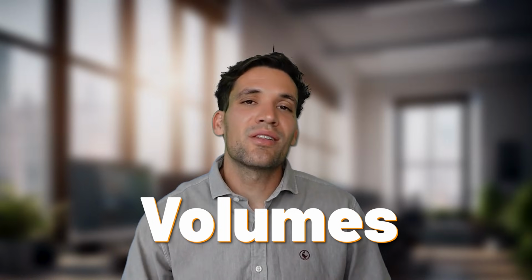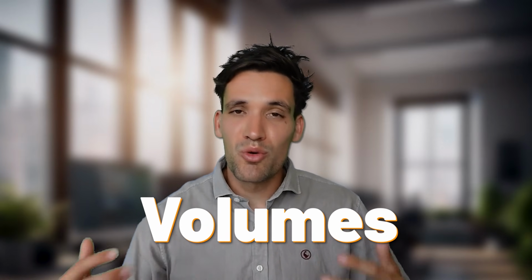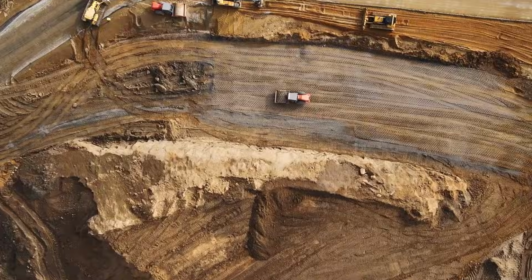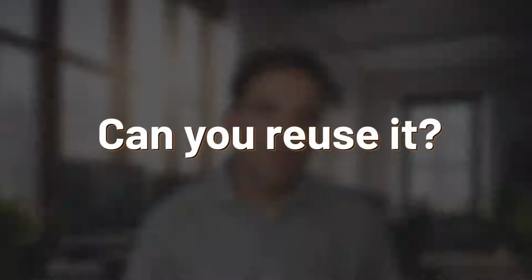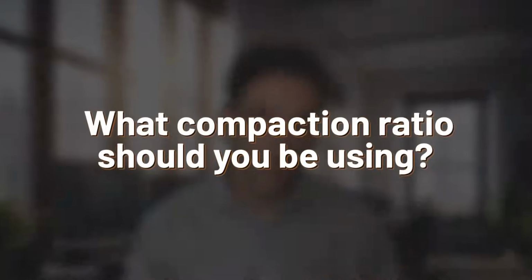Civil estimating is ultimately about volumes. You're working out the cost and the most effective way to move large amounts of dirt from one place to another. It's fundamentally a logistics puzzle. Where does the excavated material go? Can you reuse it? And what compaction ratio should you be using?